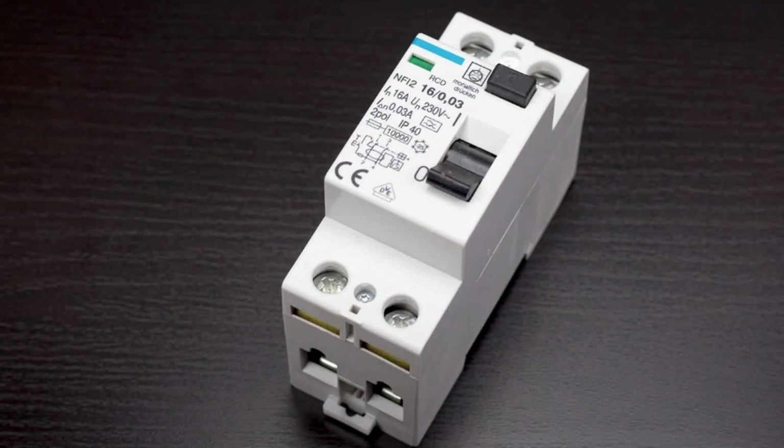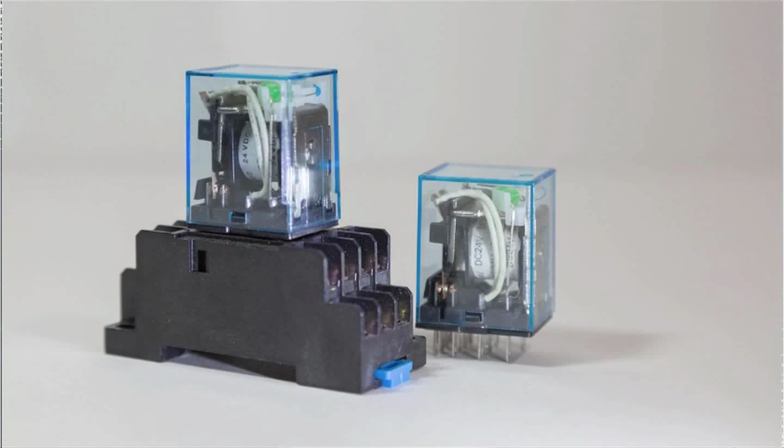For example, circuit breakers use thermal or magnetic triggers to detect and isolate excessive currents, while relays monitor and control circuits to prevent overloads or overheating. Residual current devices further enhance safety by detecting leakage currents, which could otherwise pose a shock risk to personnel.